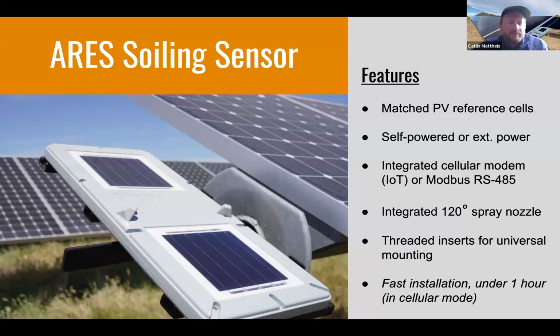There was a question on accuracy earlier. Essentially, we use a PV device, with one surface that is automatically cleaned every day and one surface that is collecting soiling loss along with the rest of the array. We measure direct irradiance based on short circuit current using this model. It is referred to as method 2 in the IEC standard for soiling measurement.